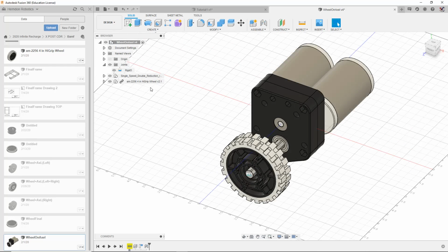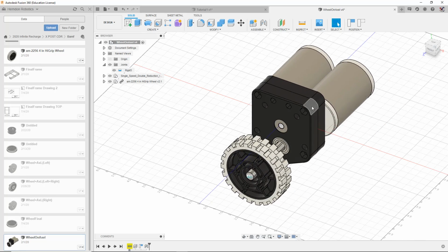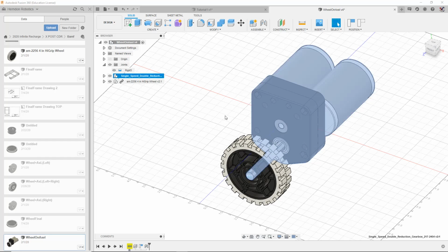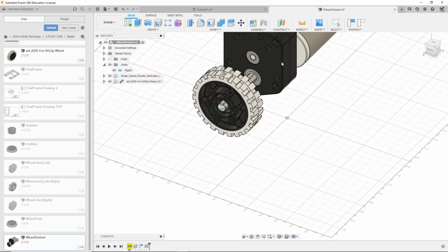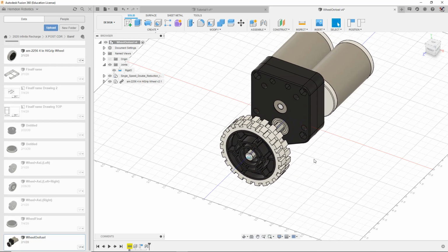And the whole component got moved, because that's basically what creating a joint does. But now if I moved it before, what would happen is if I just move this part, this wheel would not move with it. Now I move it like this, and it moves with it. And people say, oh, well, the joints don't make sense, it takes a bit too much time. How often am I going to move parts? And you could just select the parts together.